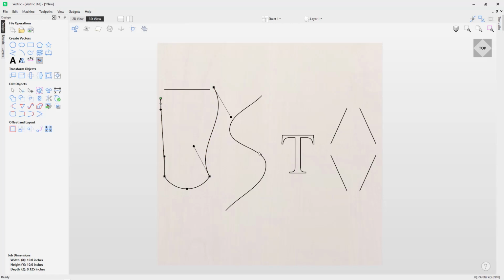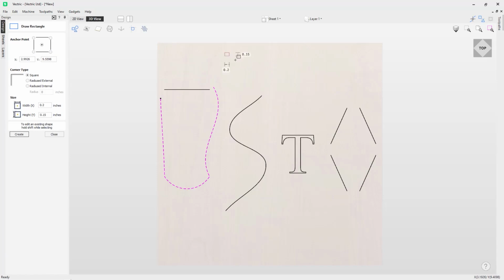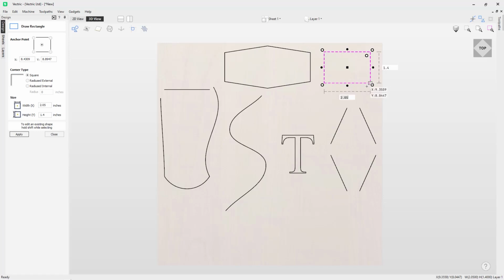Now we're actually going to move on to look at an open vector, but before we do that, I'm actually going to draw a shape. And I'm going to come over to one of our shape tools. I'll use draw rectangle in this case. And I'm going to just draw a rectangle at the top here. And what you'll notice is if I press N on the keyboard for node editing mode, I can now edit this live while still in the form for the rectangle. So if I wanted to make any manipulations or changes to the rectangle while in the form, I can do that, and then I can apply those, and then I can go back to hitting escape, and then I can indeed draw a new rectangle after I've done that. So really powerful tool in that you can node edit while you are creating your shape, and then go and create another shape after that as well.